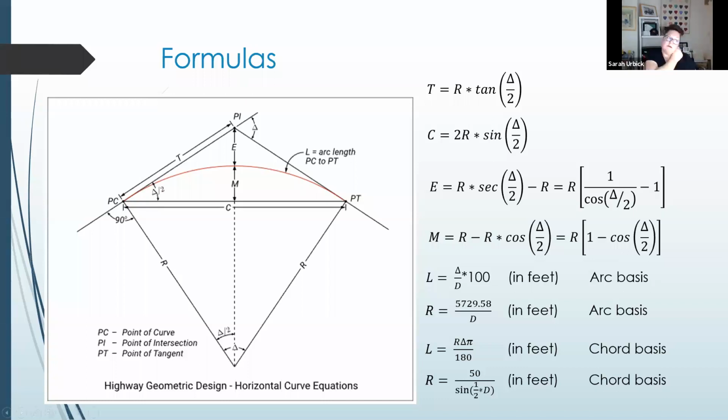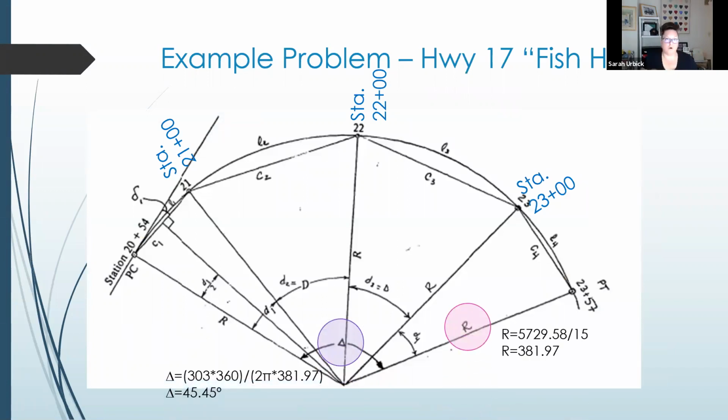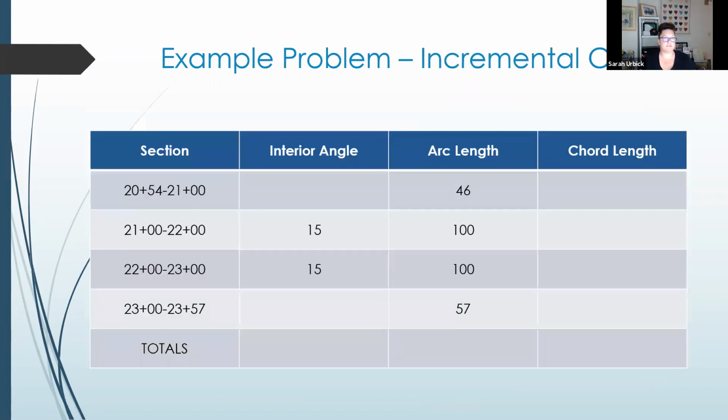All right, let me jump ahead here. So we've come up with our whole angle. We've come up with our radius. We know the full length of our arcs, right? We know, broken down into those 4 segments, our 2 segments where our arc length is 100 feet, and then the perimeter, the little extras on the side, we know what those arc lengths are.